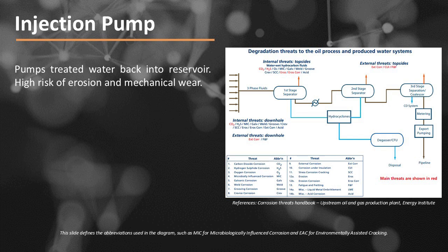Number 3 is mechanical wear. Continuous operation under high pressure and flow conditions causes mechanical stress on moving parts. Bearings, seals, and shafts are particularly vulnerable. Vibration, misalignment, and cavitation can accelerate wear and reduce pump lifespan.